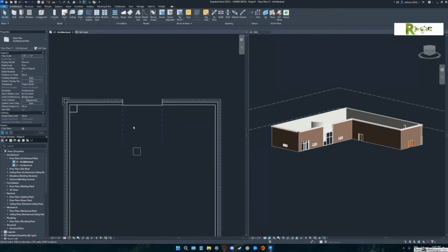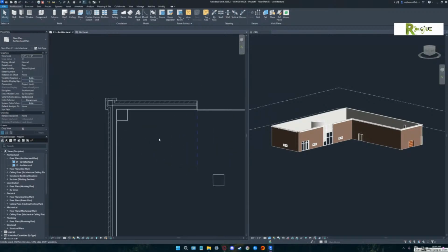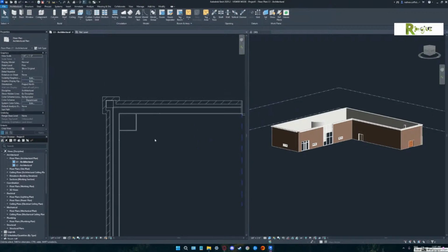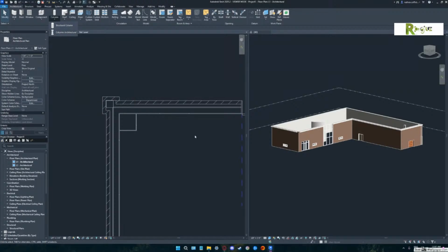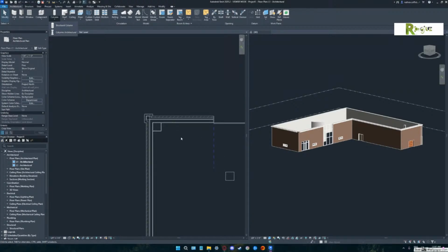So my big point there was the difference between an architectural column and a structural column. Most people don't realize if you make an architectural column that it'll do that job of wrapping. And it's only if they're joined, and we will have a way to unjoin those. Now, zoom back out, and I want you to then pick the roof command.